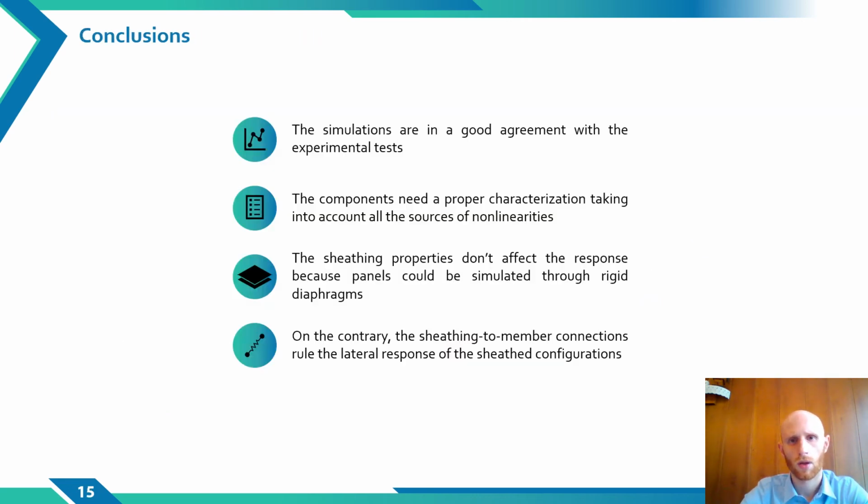In conclusion, we have seen that the simulations are in good agreement with the experimental tests, but these results have required a proper characterization of the single components, taking into account all sources of nonlinearities. Finally, we have seen that the sheeting configurations are mainly ruled by the behavior of the connections rather than the properties of the sheeting itself.